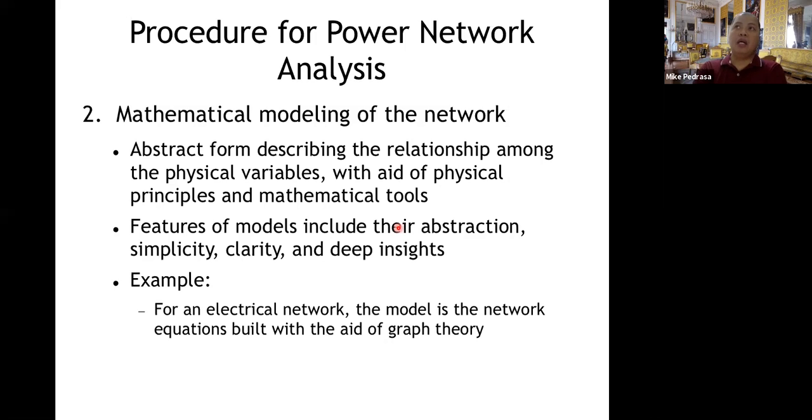Now, if we have a big network, then it will be made up of all those pi equivalent models. So we have different buses that are interconnected to each other. For an electrical network, the model is the network equations built with the aid of graph theory. In fact, that's what we're going to do in a few minutes.